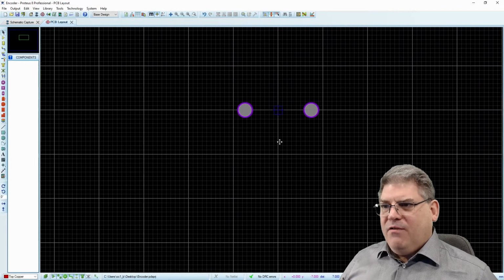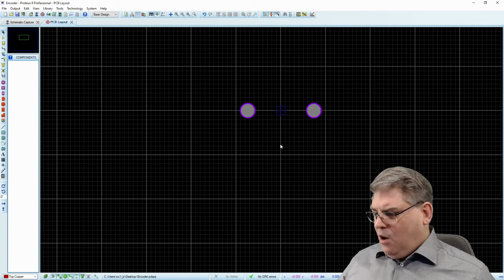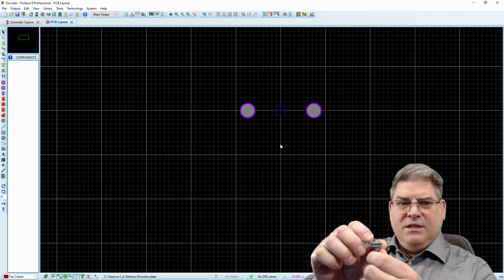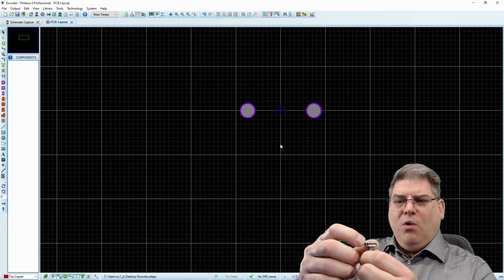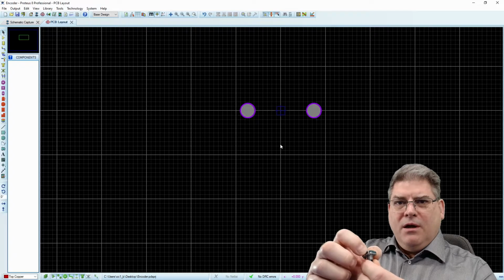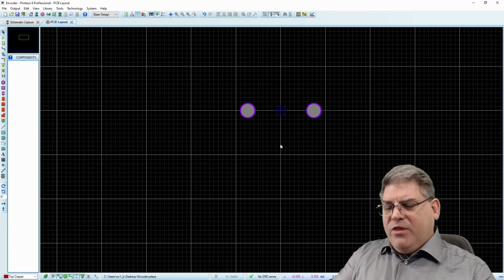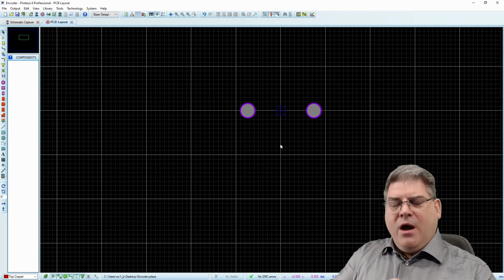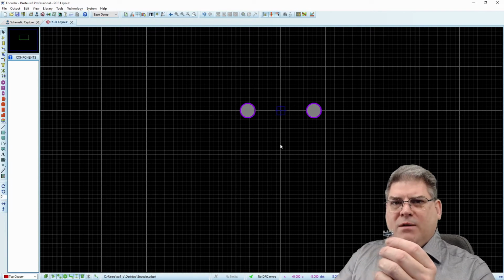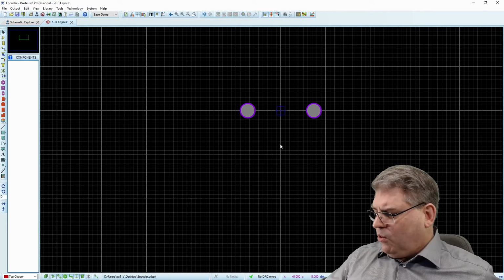And so there we have our two holes, which are for these little guys here that will hold it from rotating if there's any friction. One thing we don't want to do is rely on our solder points here to do any mechanical holding. All right.